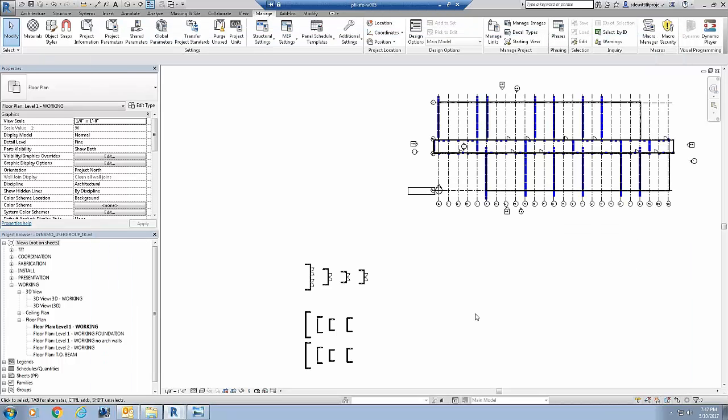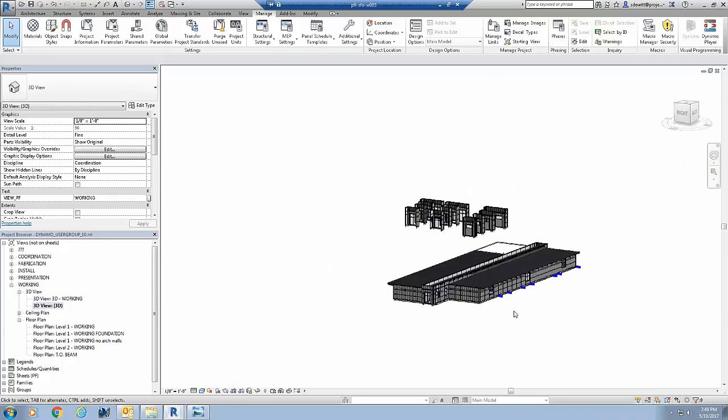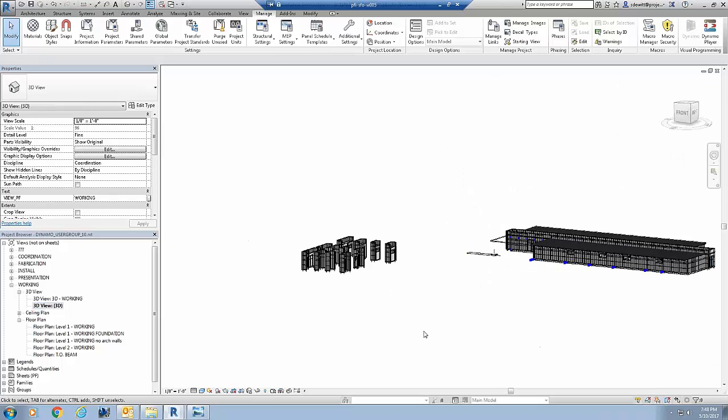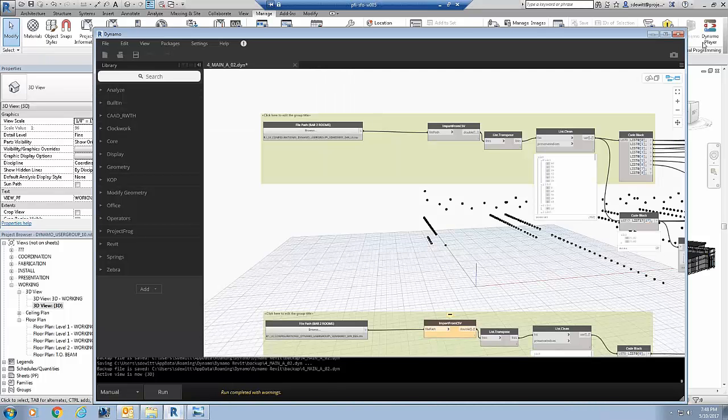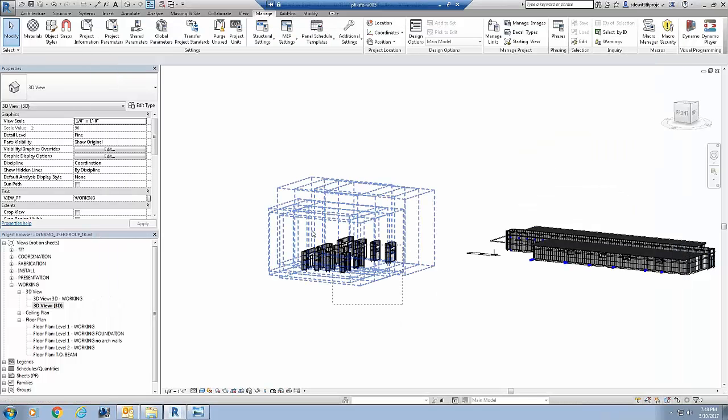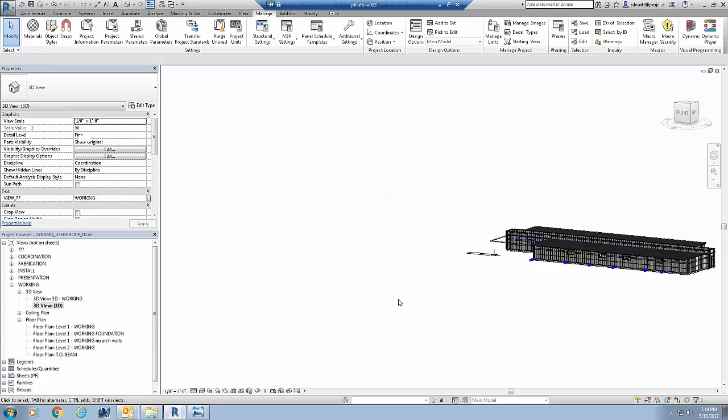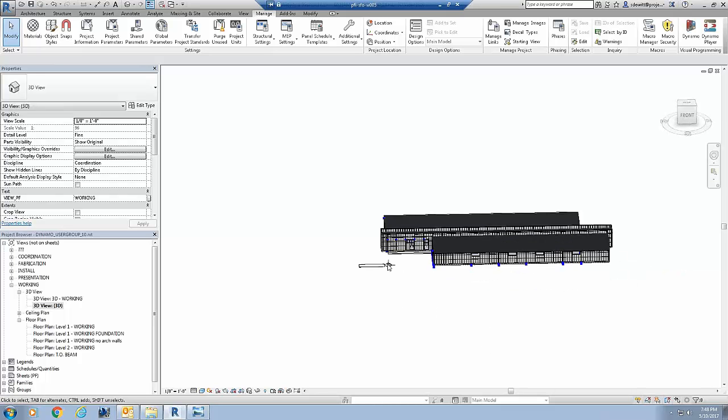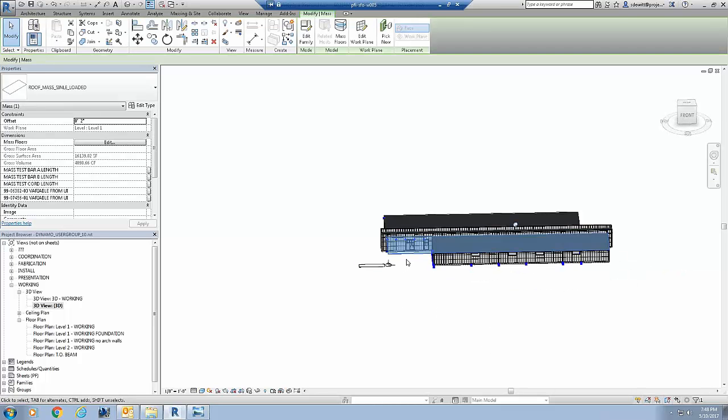We've written 4 Python scripts, I think, for some of our more gnarly geometry, for some of our more gnarly rules, I should say. The data we get from the web app is abstracted, and we have to de-abstract it and map it to real families. So we have a couple of external reference files that we use Python for. Python's easier to grab a file, a CSV or an Excel file, and read a bunch of data in.